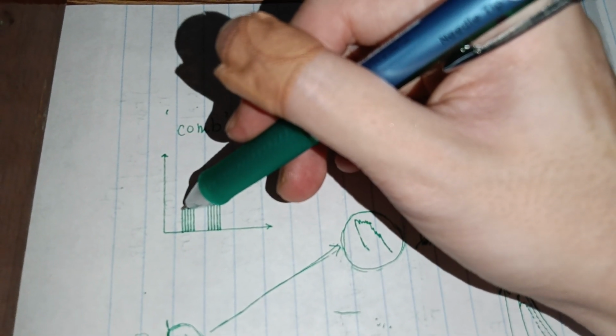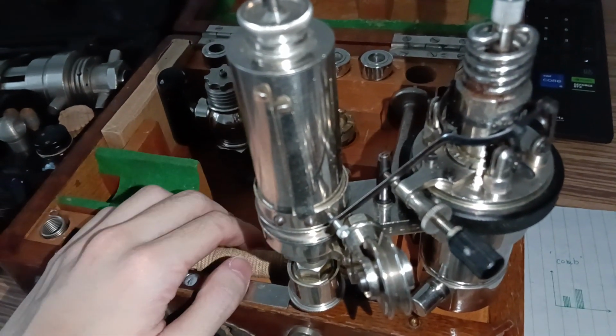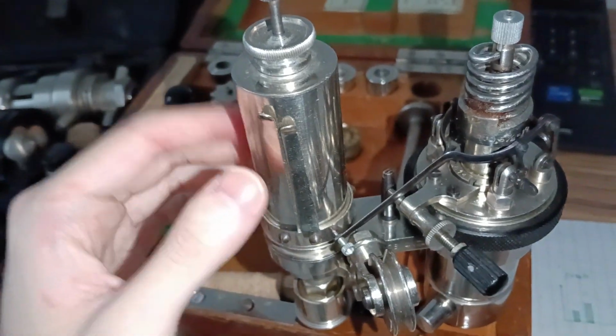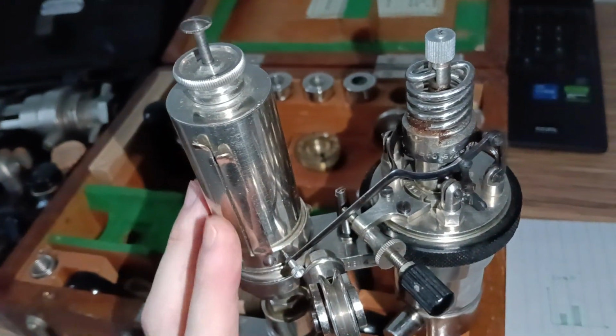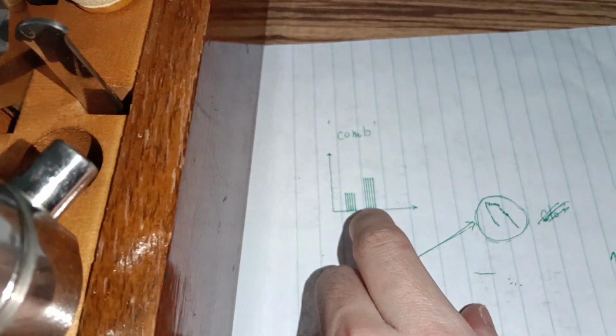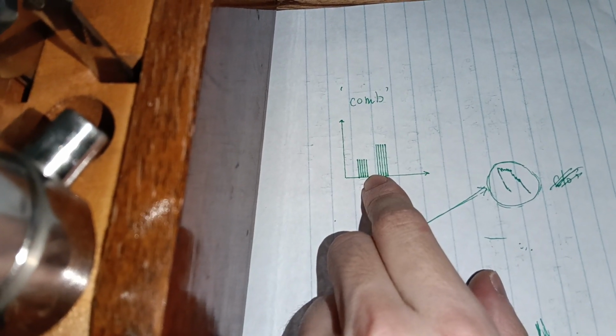So you can notice that these 5 shorter lines are actually the compression peak pressure. Imagine that if I don't connect this cord to any of the activating mechanism, if I just leave it, this one will just move upward and downward during the engine, then it will make a straight line, right?